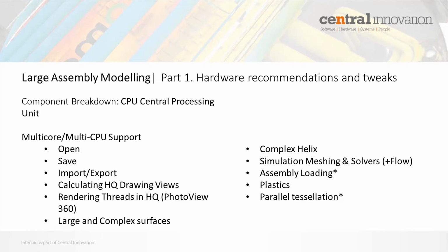However, SolidWorks doesn't use low-level modeling algorithms on a one-to-one basis, and therefore it's a bit difficult to ascertain the overall effect. But where we do see multi-core being used is in open. So if we're opening parts, it can open multi-threaded, and for assemblies as well. Save operations, import, export, calculating high-quality drawing views.